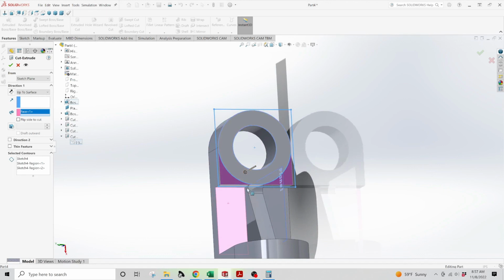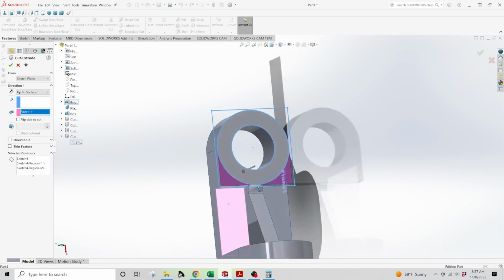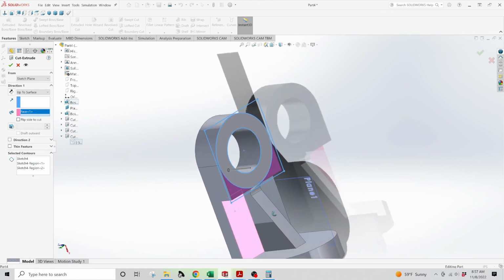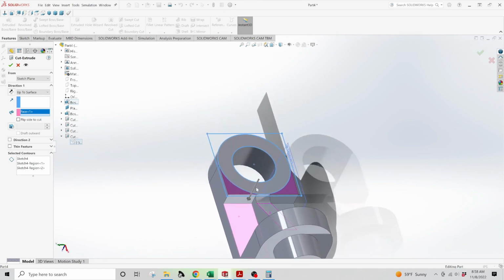Up to, because of the way that this geometry meets, trying to do this with a subtractive method is very hard. Possible, but very hard. Another easy way to approach this is actually to make this a rectangular extrusion, merge it with the surface, and then do a cut from the side. That's another method of doing it. There's also ways that you can do that using the rib tool.